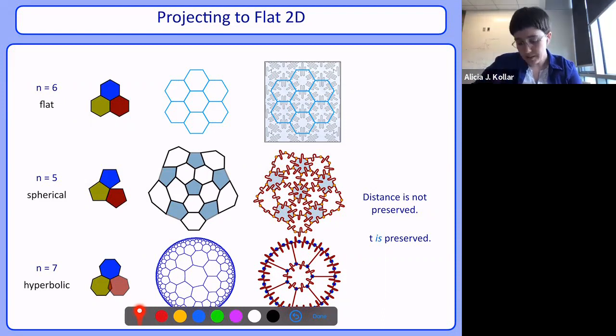And then the last thing that we need to fix is the on-site energies, so that we don't end up with on-diagonals that are different. We do that by changing the shape of the resonator. If you look here in the middle, this bond distance is relatively short, and so we use a resonator that has a fairly large meander.